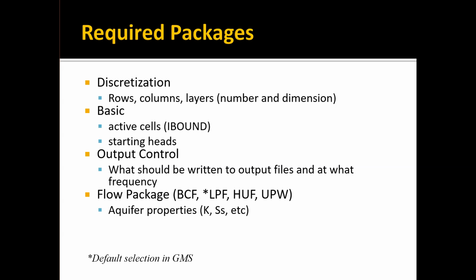Typically we use the layer property flow package, and basically the main thing you do in a flow package is define your properties, hydraulic conductivity and storage coefficient. And then you also need to select a solver. MODFLOW comes with a whole suite of solvers.